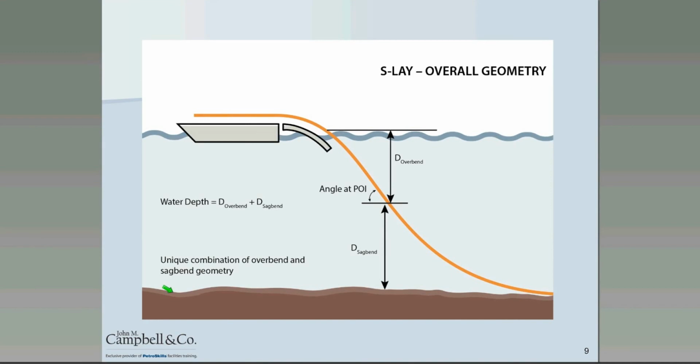First thing to think about when you talk about the tension that's going to be applied to the pipe is that I have to hold the barge in position to react against those tensions that are applied. In essence, hold the barge steady. If I don't, then it's going to move through the water. Most vessels, like the one we showed in the earlier photograph of the big semi-submersible, use anchor lines, or in some cases dynamic positioning vessels. They will use big thrusters in order to hold the vessel in place and react against the tension that's going to be applied to the pipe.